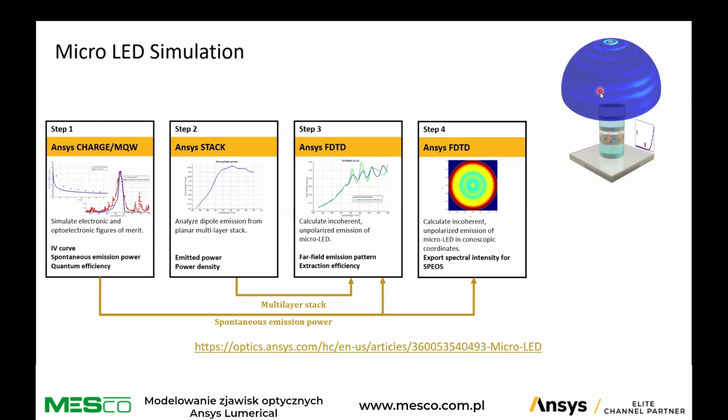But then you have multiple stacks. And what you can do is a first optimization of these layers in order to get the maximum extraction efficiency. That can be done with the stack solver, which is an analytical solver that can analyze multi-layer stacks based on the optical properties, thicknesses, and so on. And the stack solver can be used in 2 ways. The first way is for